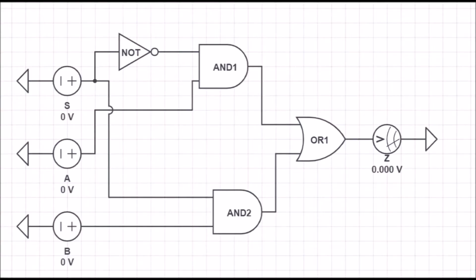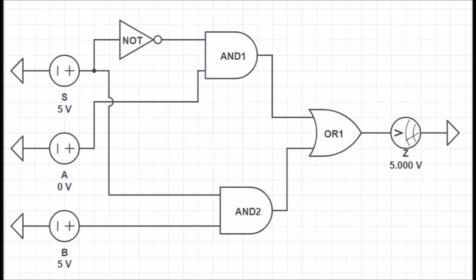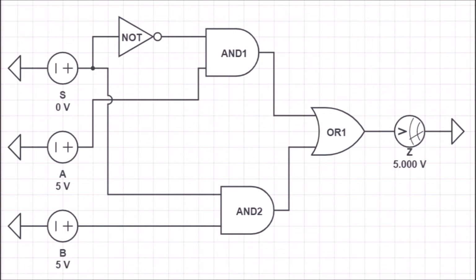Now, I've created a 2-to-1 multiplexer using Circuit Labs. This is composed of two AND components, an OR gate, and one inverter. I have attached three examples of S, A, and B varying, and the Z result being the correct Z that we saw in the first pre-lab question.